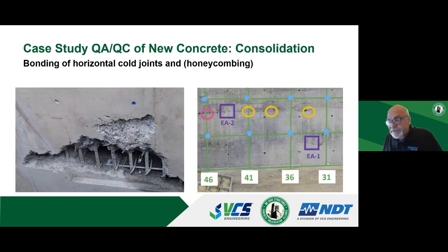Consolidation, take the forms down, you see that, nobody's happy. I want to know, well, how far does that honeycombing go into the concrete? This is brand new concrete that we just poured and paid for. Or on the right, horizontal cold joint.